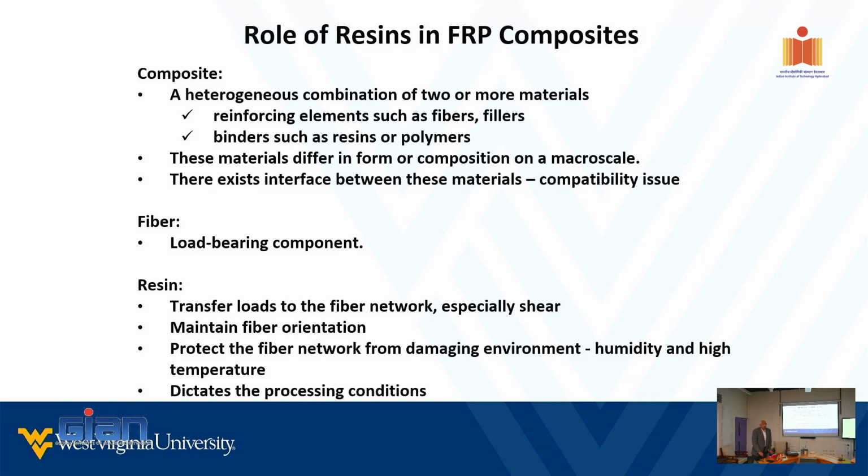Now, the typical sizing materials are silanes. Some of you may have heard of it, and titanates and all. Typically, silanes are the most commonly used. What it does is act as an interface between the fiber and the resin. That's all you need to know. I'm not trying to make you a material scientist, but at least you need to be aware of what brings the strength to the material.